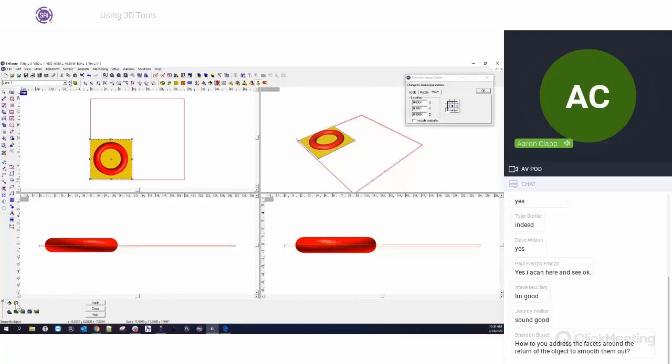We'll click on it. This is the smoothing level that allows you to do. The more that I go to the right, the more smoothing it does, and the more to the left, the less it does. There's no granular control here. So the problem is that all surfaces throughout the entire object are smoothed off a little bit. So if you only want it to smooth in certain areas but not others, this is really not the place to do that. There's other ways of smoothing off a relief if you absolutely need to.